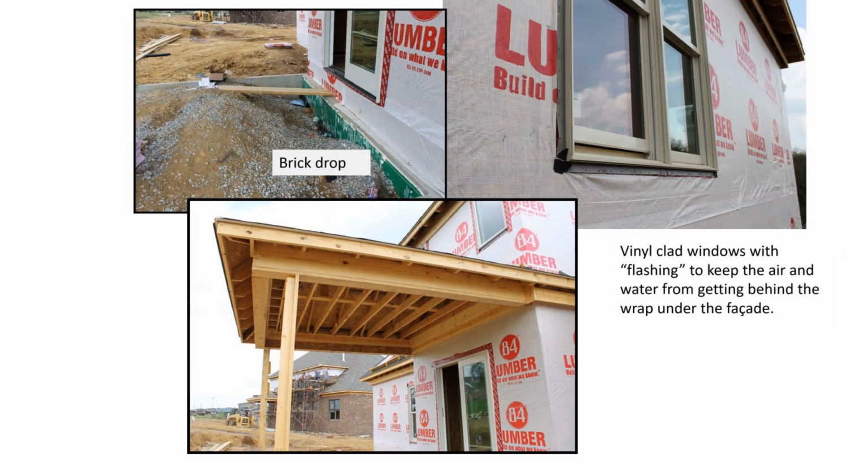This is an example of a brick drop. If you're looking at a house and you see this little space here, you know that they're going to put brick on this foundation. If you don't see a brick drop, then it's going to be a vinyl sided or aluminum sided house, or maybe even frame. But if it's this wide, you know it's going to hold a brick. This is showing the flashing underneath where they've set this window, again, to try to eliminate any issues with water intrusion. It works kind of like flashing, just to alleviate water from getting in there, and also air.